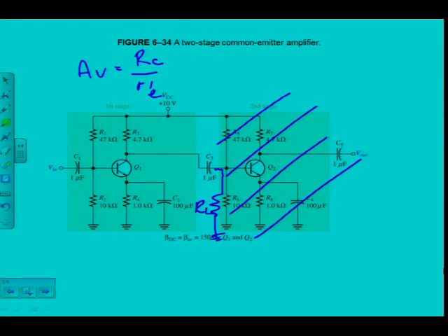Let's look at the R'E at the bottom of the line. There is a capacitor that is bypassing R4, so RE for this amplifier is bypassed. So I would say yes, R'E is true in this case. Do you agree with me?